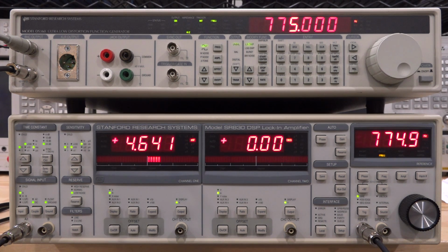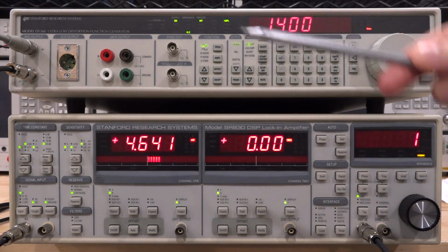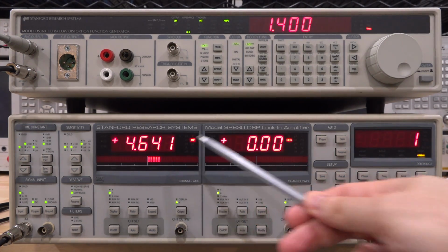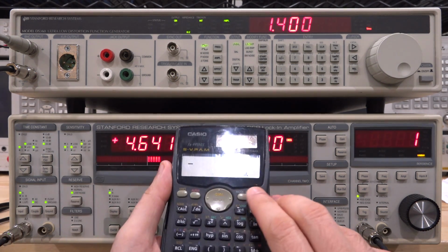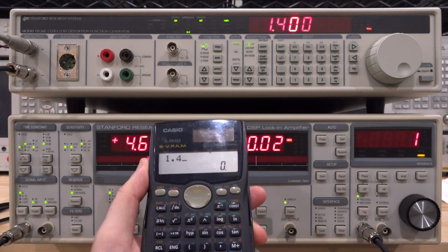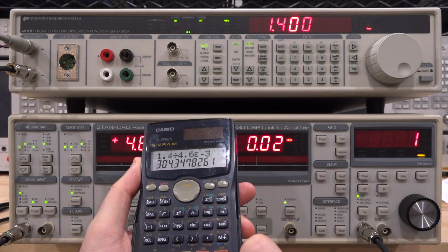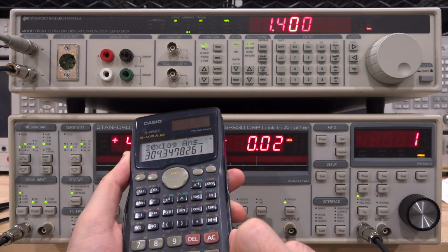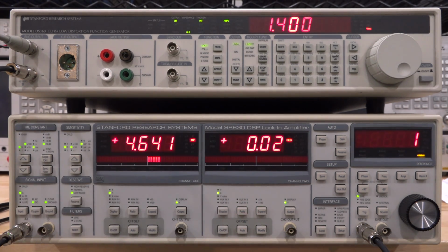So right now what are we looking at? We're looking at the first harmonic, so that's the fundamental of a signal of 1.4 volt RMS going to the filter, and when it comes back out, it's sitting at 4.6 millivolt RMS. So it's heavily attenuated by the filter, which is exactly what we want. That's the whole purpose of this, to attenuate the fundamental. Now how much is that being attenuated? Well, we can quickly calculate that. We can take our 1.4 volt RMS signal, divide by 4.6 millivolt, and calculate the 20 log of that, and we get about 50 dB, which is what we expect. Perfect. So that looks good so far.